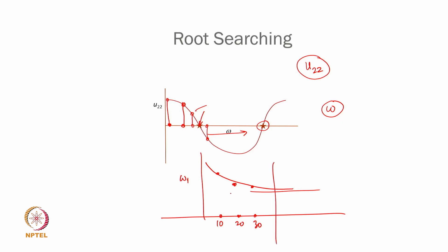So you then decide what your tolerance value is, what error you can tolerate for the first one. Typically people do it for the first 5 eigenvalues, depending again upon the rotational speed of the shaft of the gearbox. What frequencies are you interested in? The highest of those should not have a large error just because you are discretizing into a smaller number of segments, because the larger the number of segments, the more the computation increases.